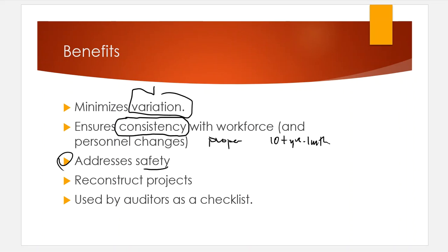This is something that an SOP doesn't really stress. A lot of times when people are trained on SOPs, they don't really take a look at this. If you are working with hazardous chemicals, how do we get rid of them? How do we work with them safely? That should be part of the SOP. It will be there. But a lot of people focus on the procedure and that is it. And by all means, the procedure is a very important part of the puzzle. But safety issues and concerns are also a thing as well. Do I dump everything down the drain? Right? That's always the question that we get. And the SOP should and will tell you how to handle that waste and how to handle the things that are coming from these SOPs as we complete and do these tests.